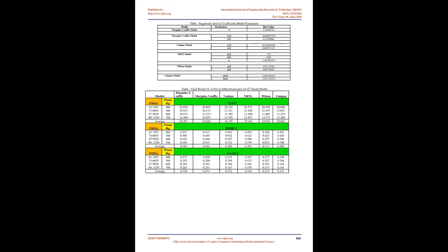By using regressed parameters, bubble T is found out. Activity coefficient model parameters are regressed using experimental PTX data. Then experimental binary PTX data are modeled to find vapor phase composition using regressed parameters, and the vapor phase composition and temperature are compared with bubble T calculated data.